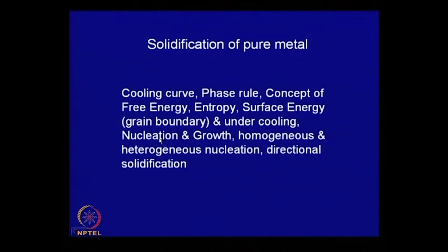We will look at the energetics of nucleation, and thereafter nucleation there is a time dependent growth process. Nucleation is probabilistic, stochastic in nature, whereas growth is deterministic, it will follow certain growth rules.